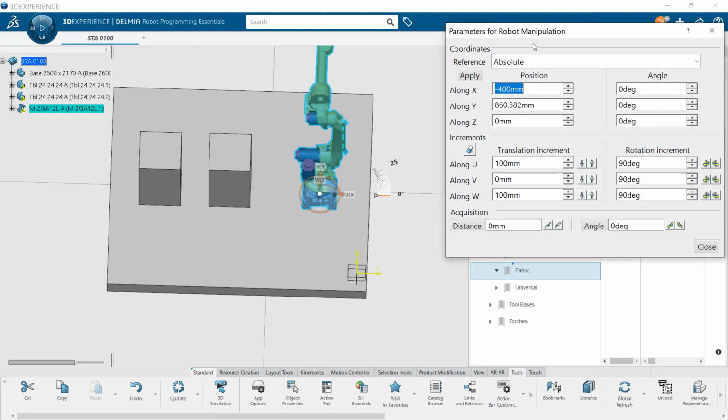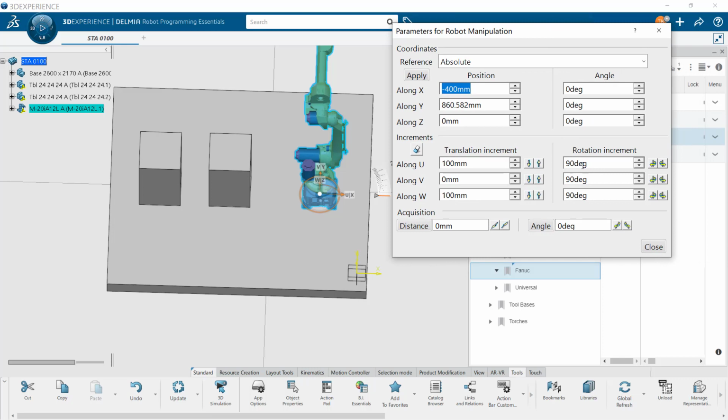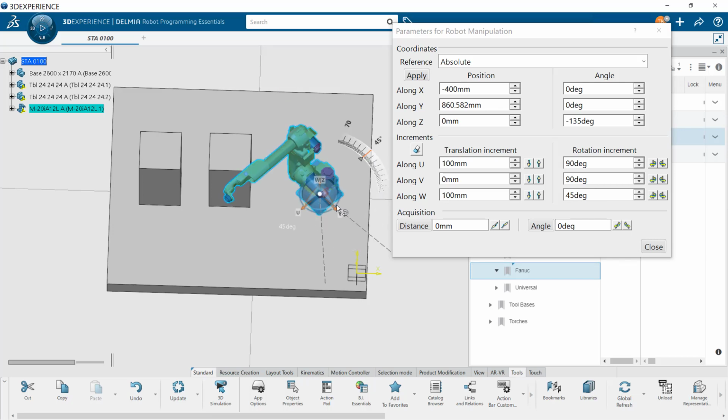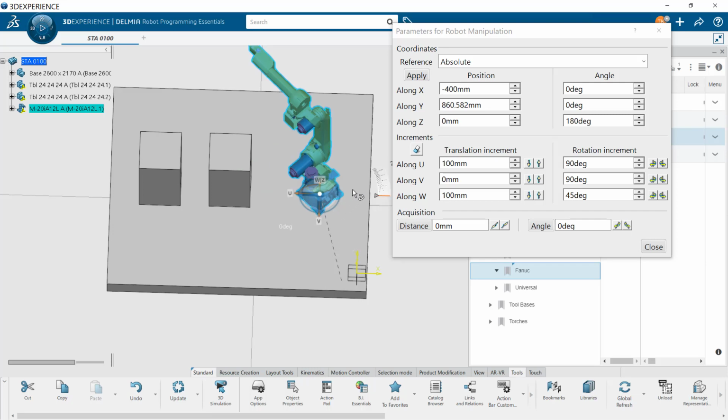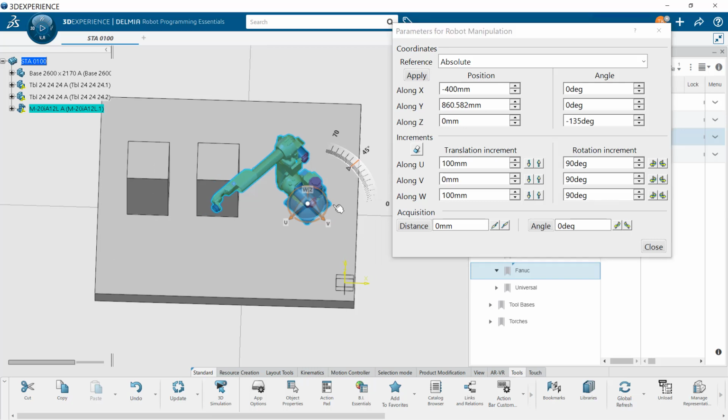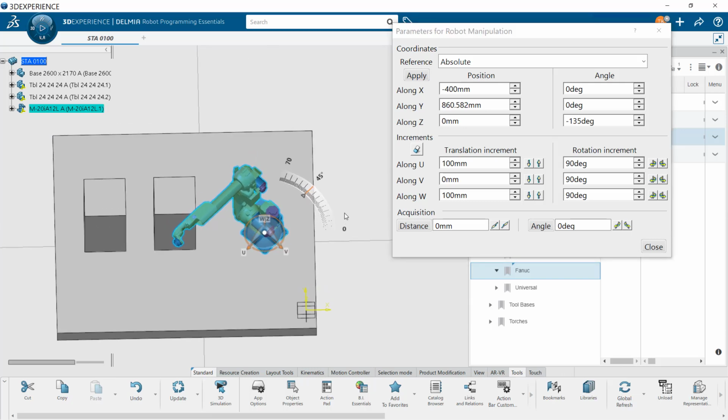When I double click on the compass, I have all my increments at 90, so I will only see 90 degrees. If I wanted something different, like 45, I have to change it to 45, and now I can get something different. If I'm not quite certain what I need, a lot of the times I'll just make this 1, and that'll work for most purposes. But it does require some skill with the mouse, because you're reading off of this call out that gives you the angle.